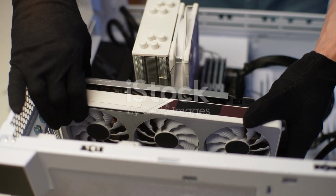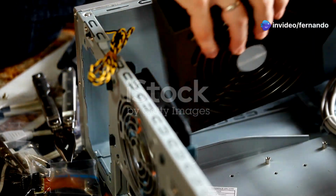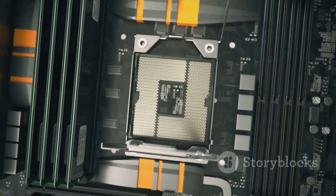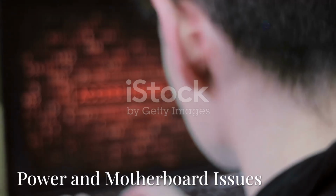If your desktop has a dedicated graphics card, make sure it's properly seated in the PCIe slot and has any needed power cables attached. No luck? Try removing the graphics card and connecting your monitor directly to the motherboard's video output. If you see a display now, your GPU could be the problem.